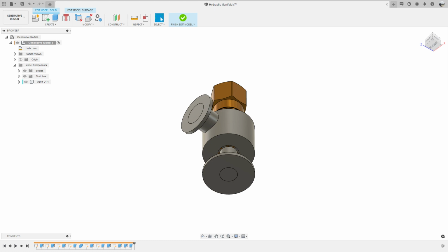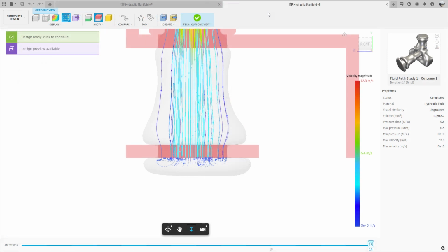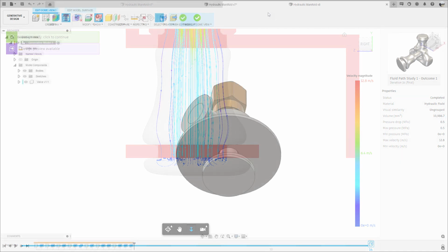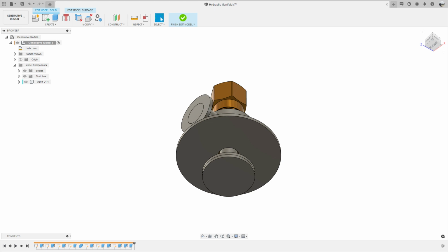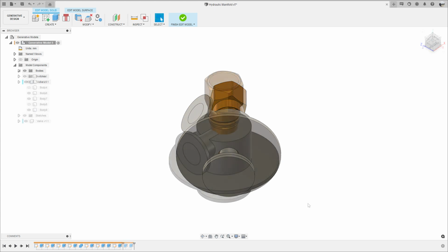After creating these bodies, you are going to create a cap on the outlet. Remember, this feature is in public preview, which means it's not all the way done and there are still some issues to iron out. The reason we need this cap now is if you don't have it, our algorithm will create a mushroom shape outside the manifold and will cause issues with our simulation of the fluid. Last, we are going to create a body right under the valve with a hole the same size as the bottom hole of the valve. This forces the fluid to go through the valve to reach the outlet.